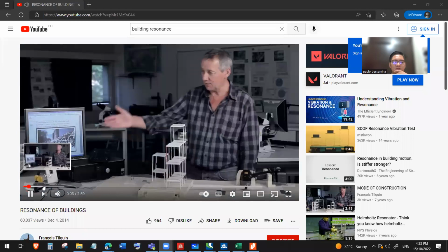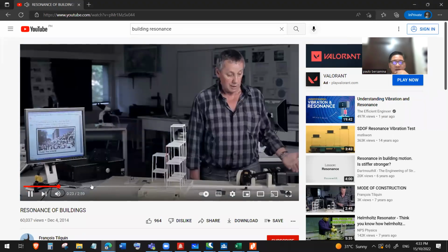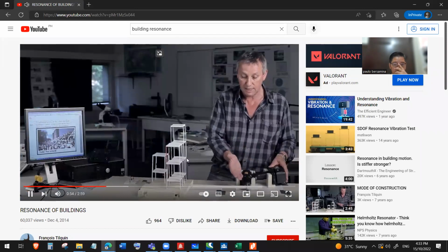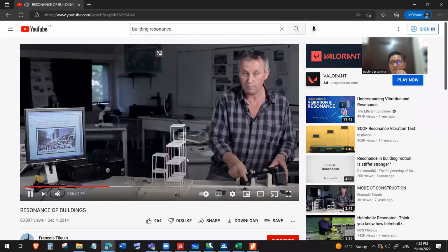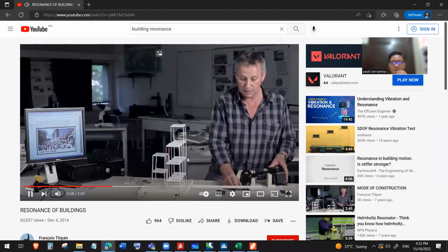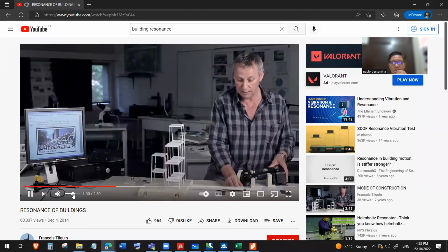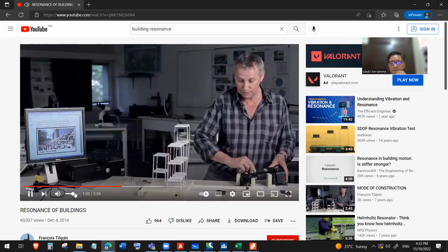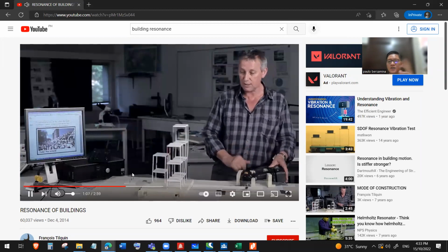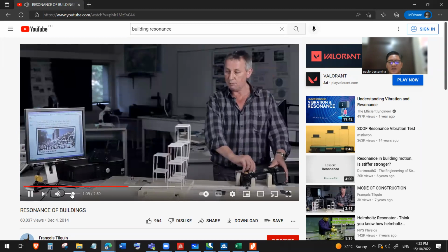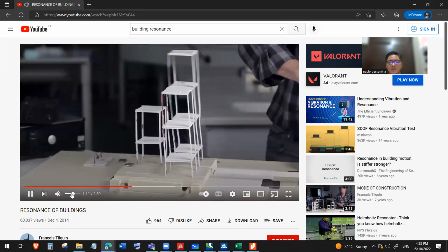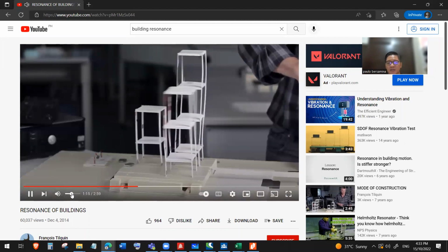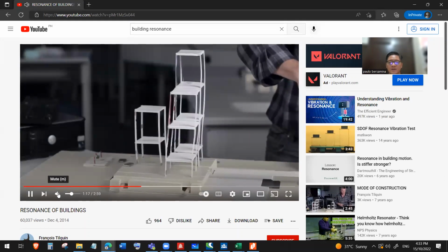When we see this kind of picture, nothing appears because the eccentric is not far from the axis. So now I am putting this far, and now I see the beginning of this system working. So now I'm going to study the resonance. As you will see, the big buildings resonate. I'm increasing the speed. And now, yes, the big building, and now the intermediate building resonates.